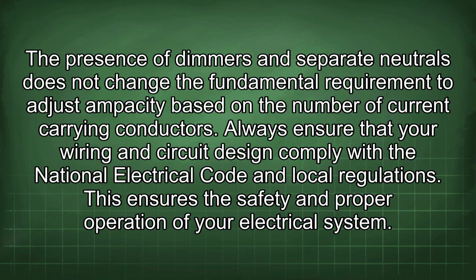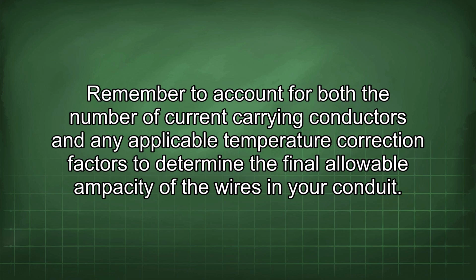The presence of dimmers and separate neutrals does not change the fundamental requirement to adjust ampacity based on the number of current carrying conductors. Always ensure that your wiring and circuit design comply with the National Electrical Code and local regulations. This ensures the safety and proper operation of your electrical system. Remember to account for both the number of current carrying conductors and any applicable temperature correction factors to determine the final allowable ampacity of the wires in your conduit.